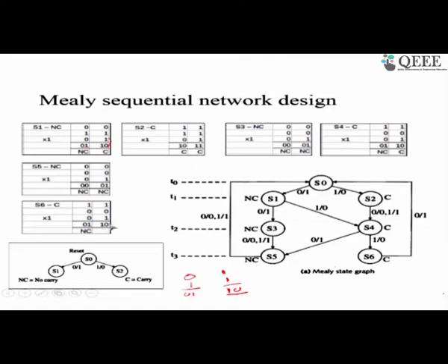But if you look at this one, there is a carry that is being generated, but we will see that in a BCD to XS3 conversion no carry will be generated after the 4th bit is processed. So what we conclude here is that this combination will never occur in this state S6. When you are in state S6 the last bit has to be 0. So that is why this condition will not occur.